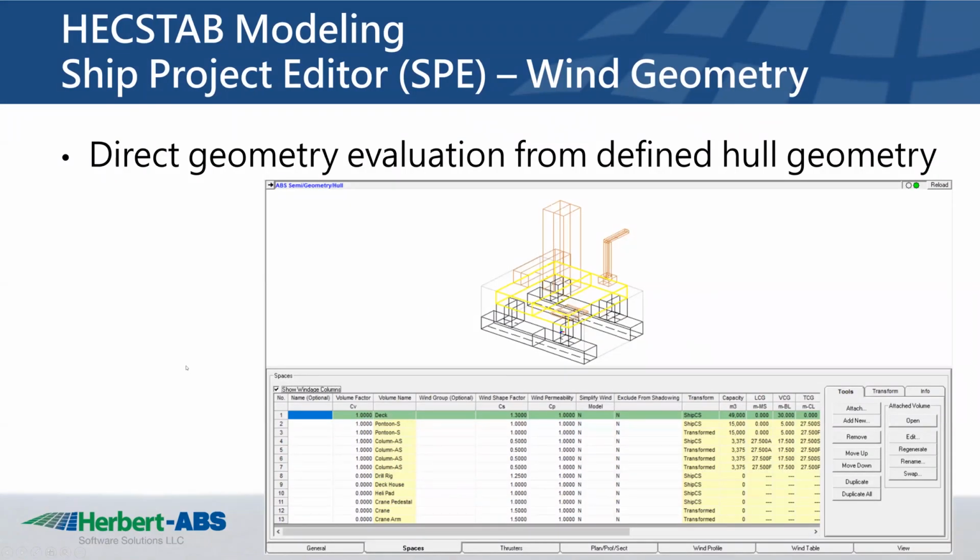And our third and final, and sort of the new approach we're going to be talking about today, is the idea of wind geometry, which is doing all the wind overturning moment calculations directly from the geometry defined in the hull.